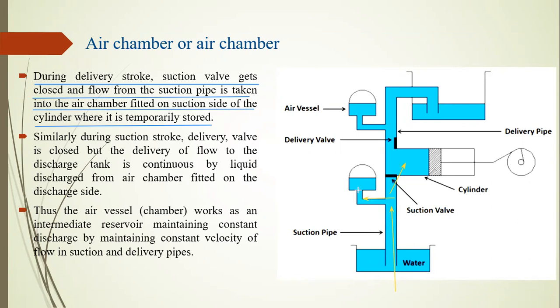Here the air chamber stores water temporarily. Then, during the suction stroke, the delivery valve is closed, but the flow to the discharge tank is continuous because of the liquid discharged from the air chamber fitted on the discharge side.